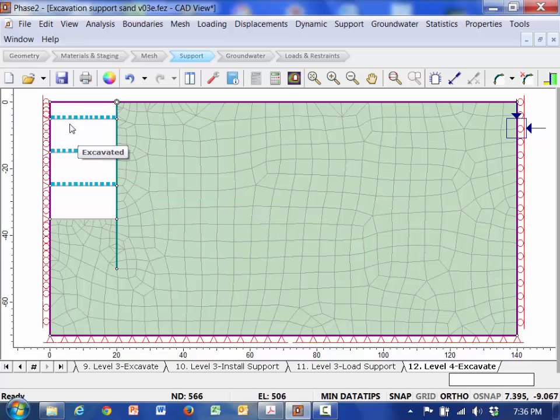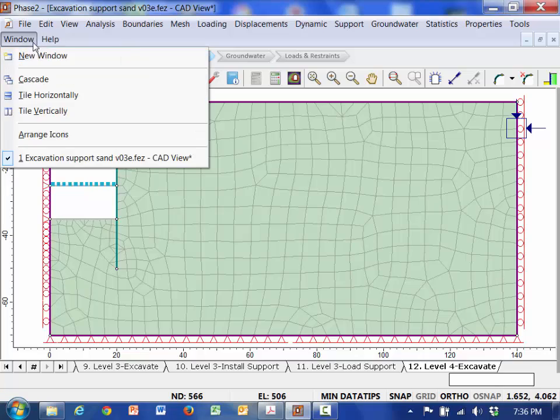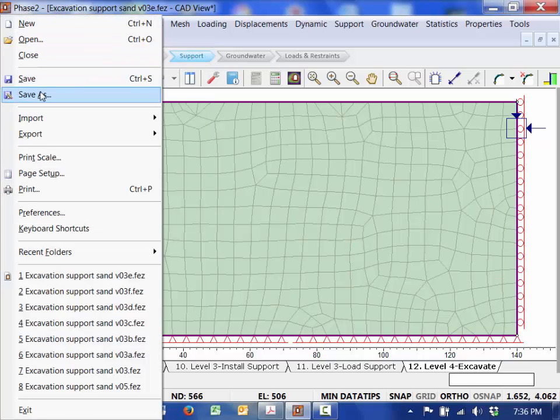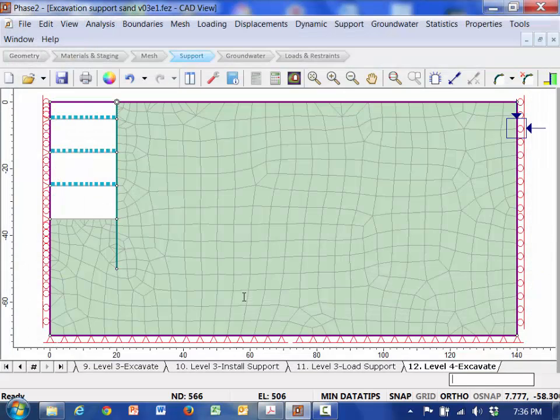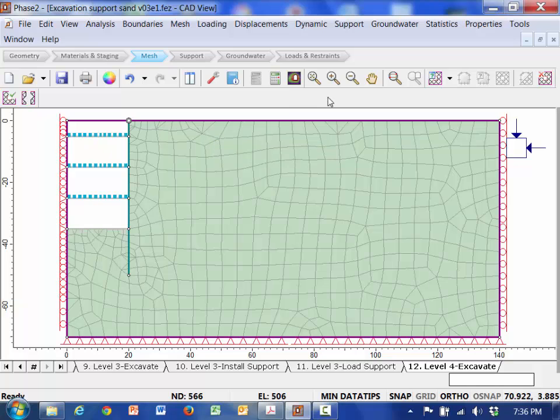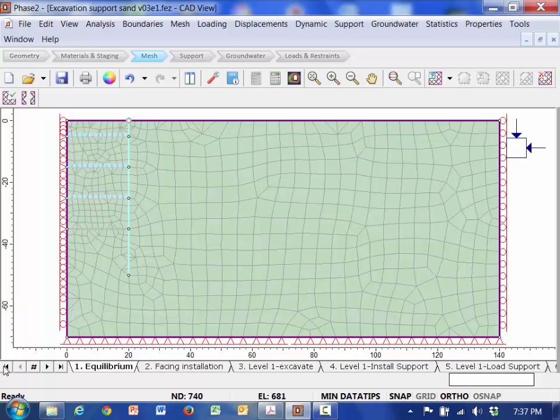All right, so then you definitely want to save. And now we're ready to compute. Before we compute, I don't understand this exactly because you set the mesh up, but you definitely want to come back here, and there's two mesh checking algorithms here.